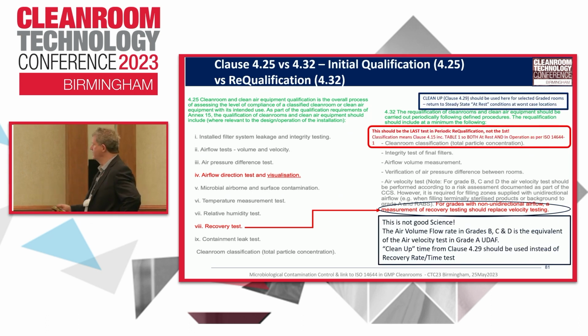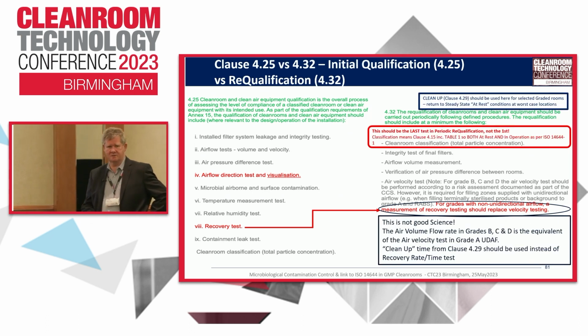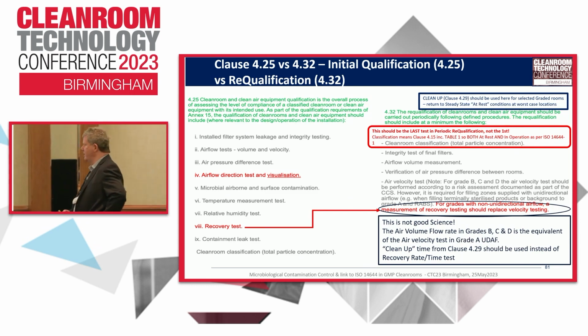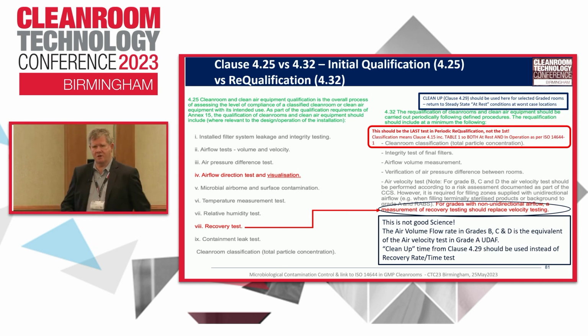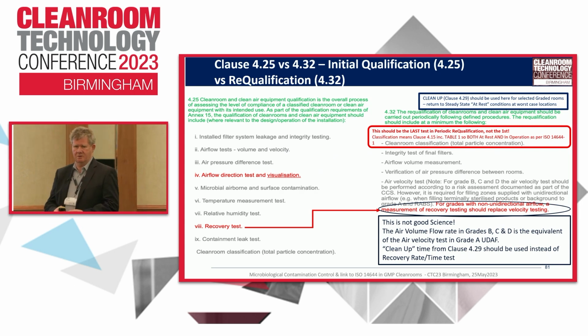Now, that's just bad science. The equivalent of the air velocity test in grade A in unidirectional flow is air volume flow rate. It's not a recovery test. And when you do recovery, you've got to put a challenge in. So you're now contaminating your grade A environment, because you've got to put something in as a test aerosol to look at the recovery rate. And I'm suggesting, as others are, that you use cleanup time.